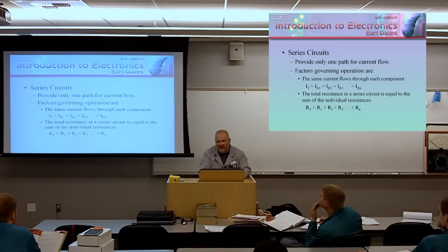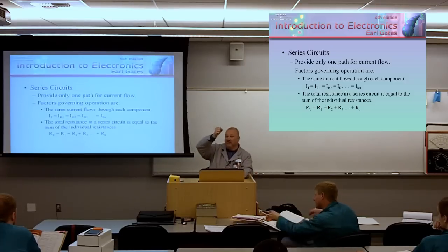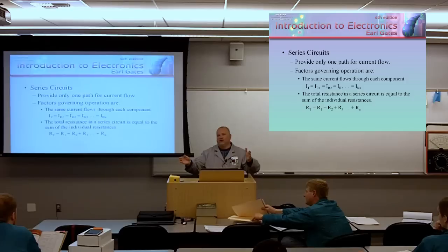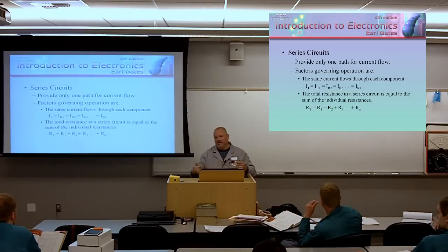Always additive. And that includes the resistance of a bad solder joint, the resistance of a bad splice. Remember how I said the power company will actually use thermography and look and say, wow, we've got a splice up there and it's generating a lot of heat. We've got to shut that section down and replace that, because it shouldn't be generating any heat if it's a good splice.